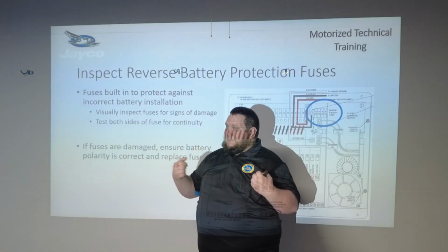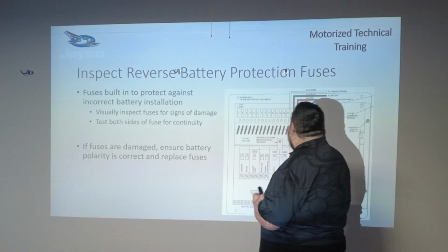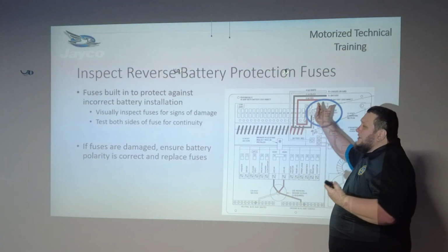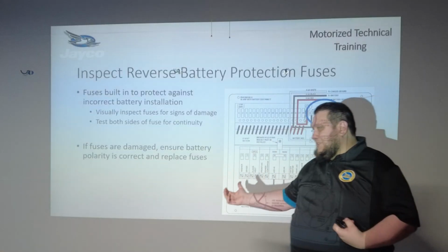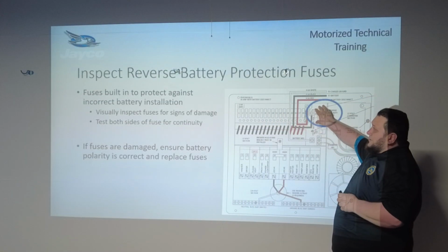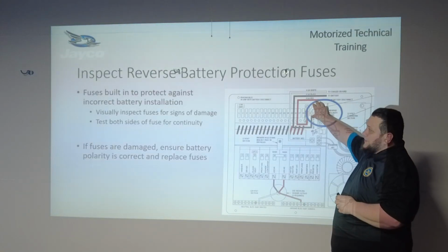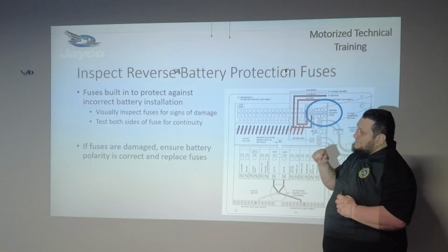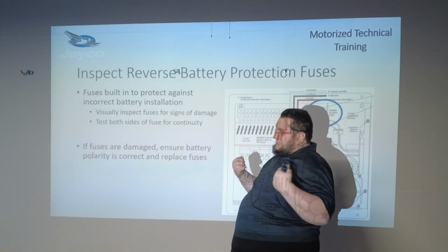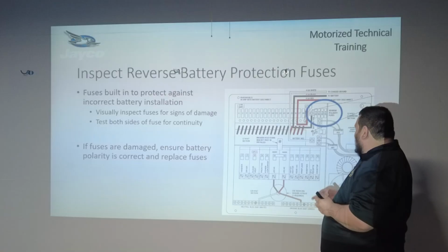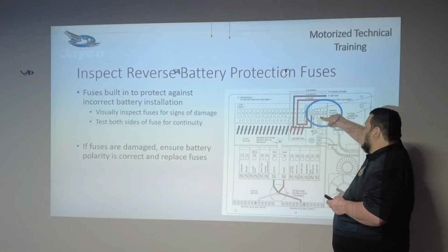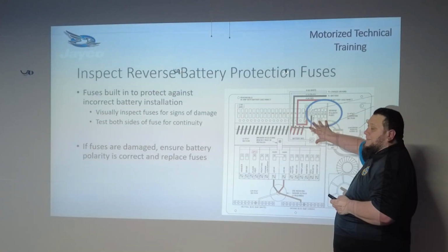One of the most important parts when you're troubleshooting a load center are, as Sean pointed out, those 4 little yellow fuses right here. Some converters will have 2, some will have 1, some will have 4. Either way, these fuses are called reverse polarity fuses. What they do is protect against, let's say the technician had to get in here and work, and accidentally hooked up the positive to the negative and the negative to the positive on their output here.